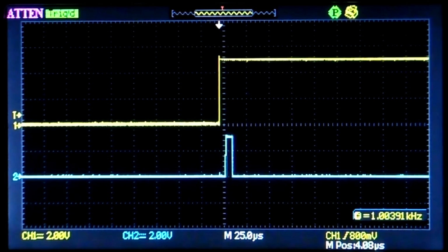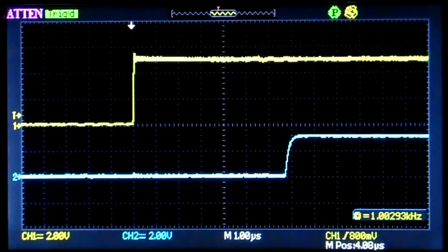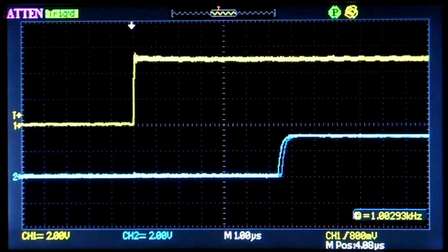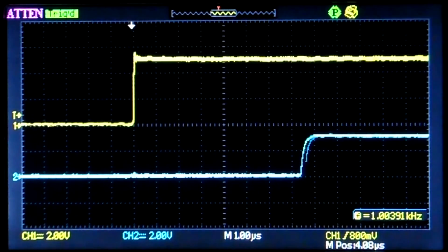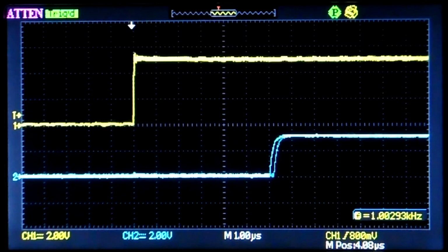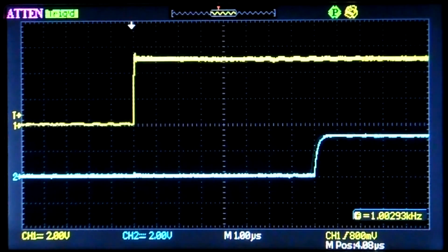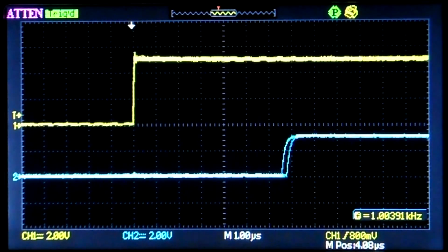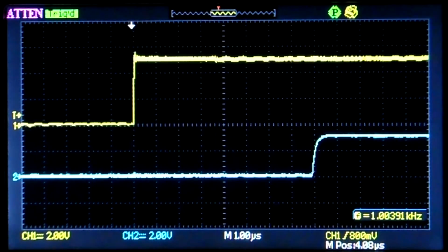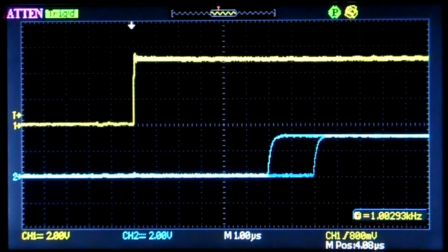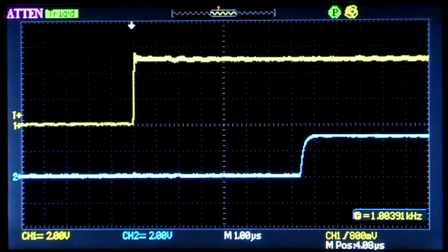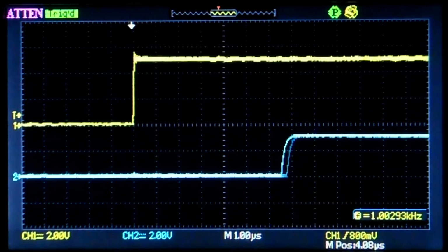Now let's measure latency. As you can see, latency is not constant. There is a jitter. Hardware and software are the cause of jitter. Time scale is 1 microsecond per division. To the naked eye, latency is around 10 microseconds. It is consistent with other tests reported. In fact, latencies reported are average values. This test gives us a first approximation to measure interrupt latency.